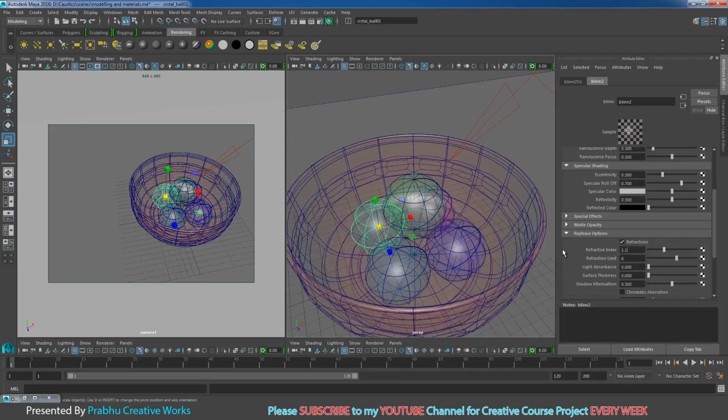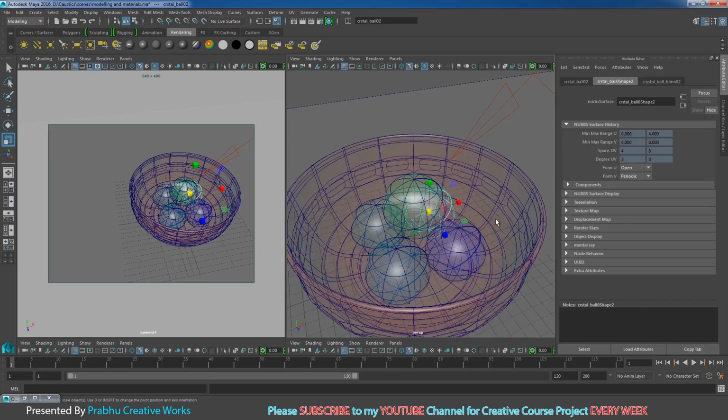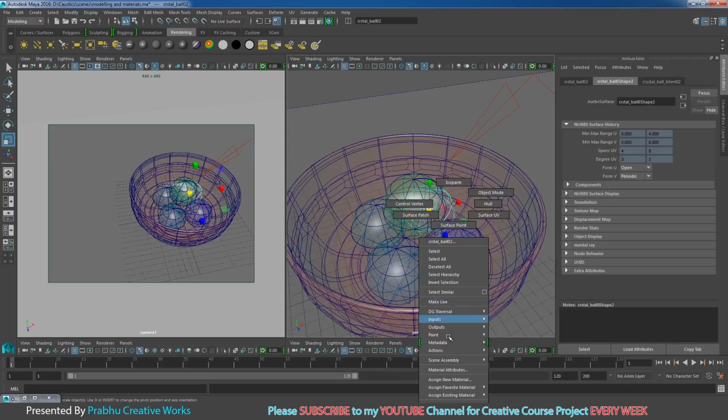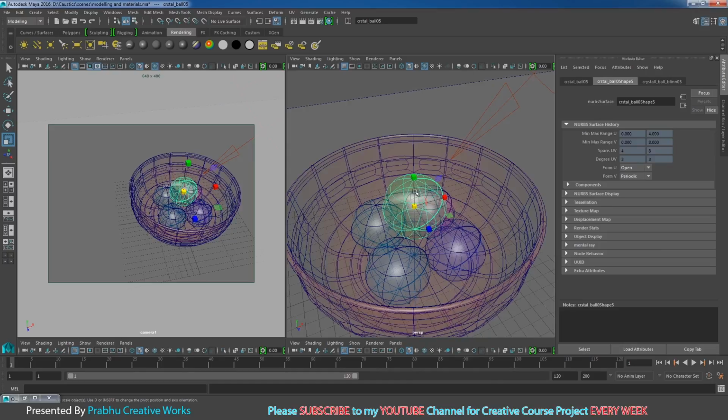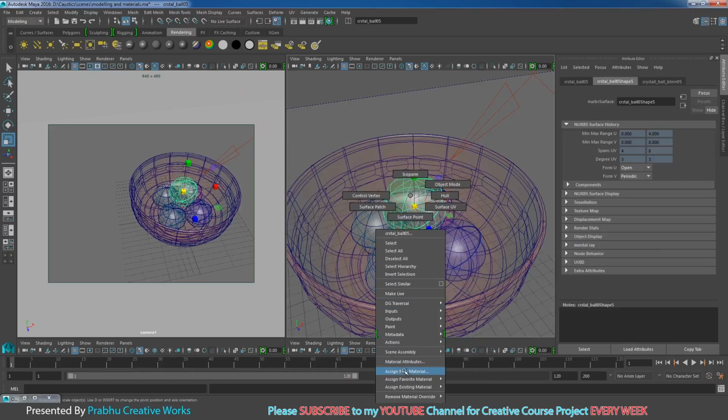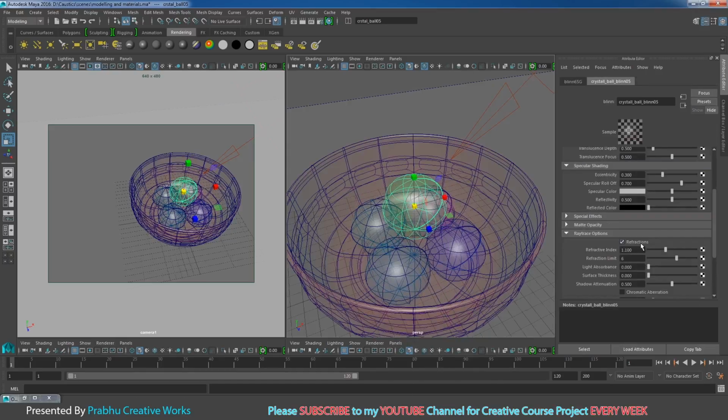I will give 1.1. Do the same thing on each of the others: right click, choose material attributes, turn on refraction, and give 1.1. You want to give all the crystal object materials a 1.1 refraction.